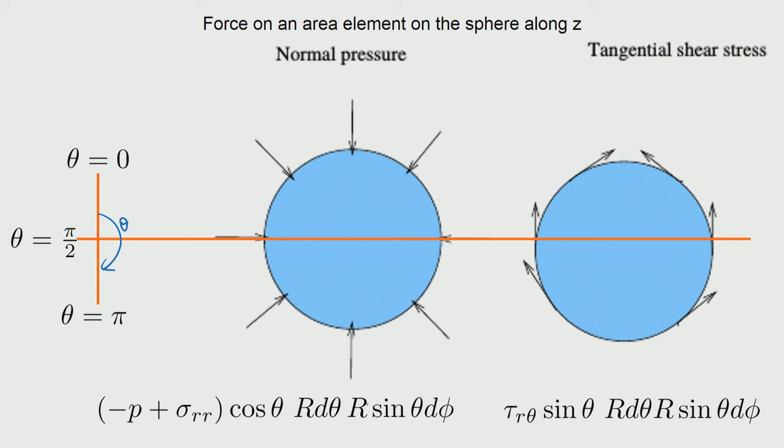So, if you look at how the normal stress has to be computed in the vertical direction, you could see that here the pressure would come straight away as minus p, and cos theta is 0. So, minus p it will come, and sigma is actually going to be plus sigma RR, and here actually it will be 0, and here it will be again in the minus direction. So, you could already see that this part is basically taking the stresses and giving a component in the z direction.